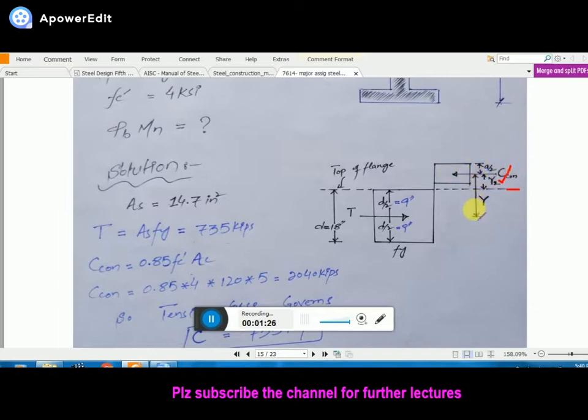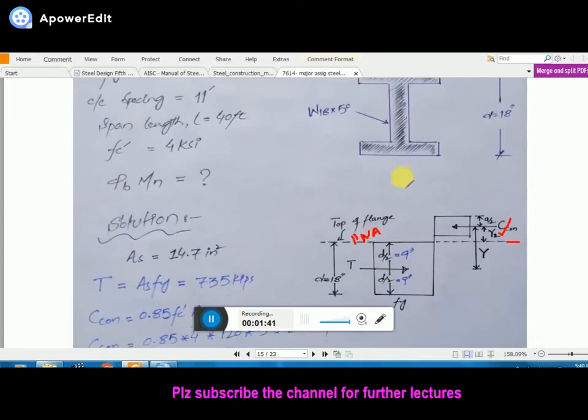You should remember this y2 is counted from the plastic neutral axis location. In this case we are assuming that the plastic neutral axis lies at the top of the flange, so make sure that y2 is measured from the new plastic neutral axis. Please confirm it.